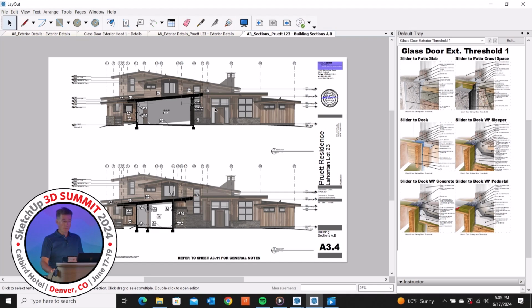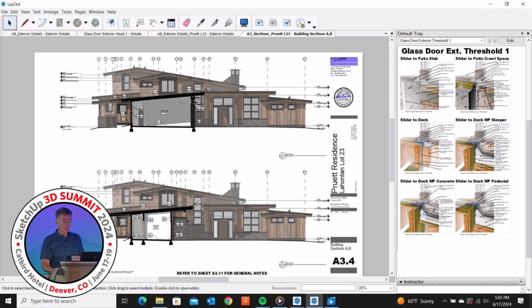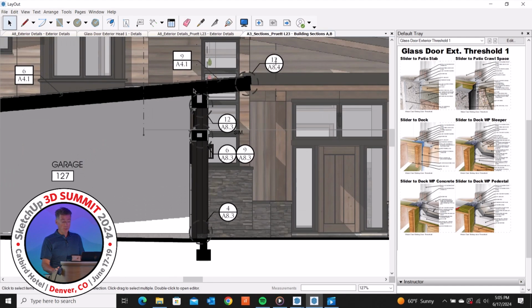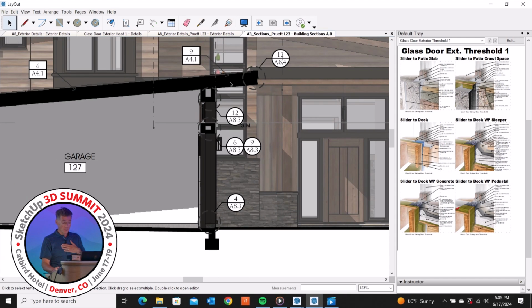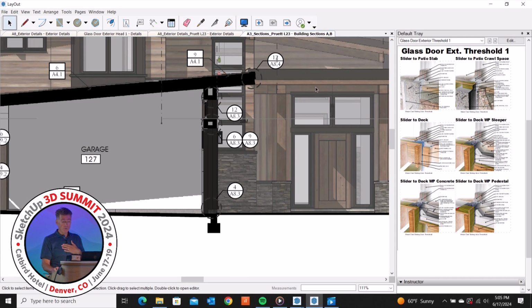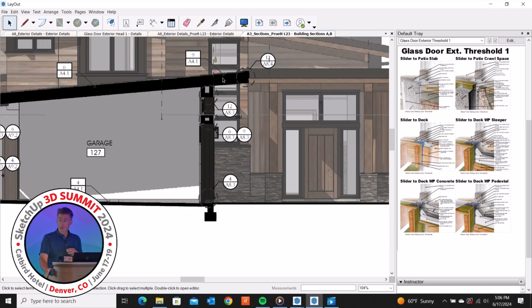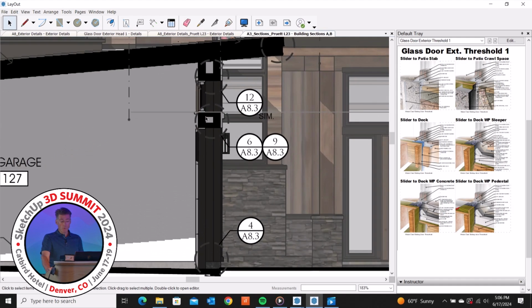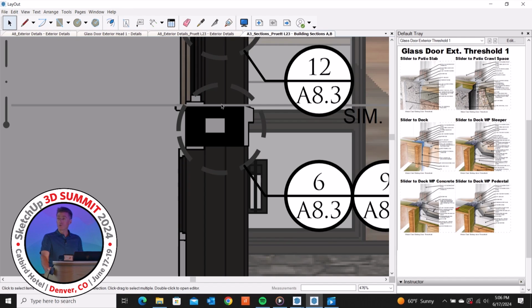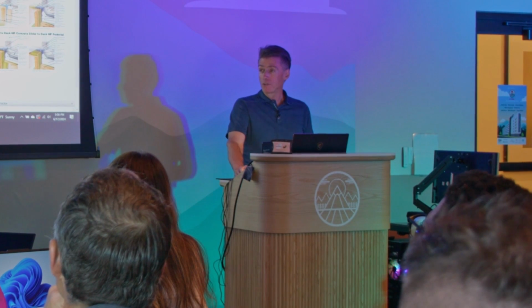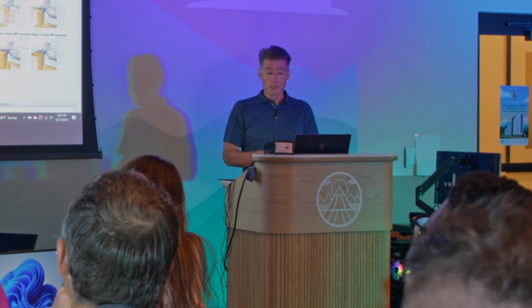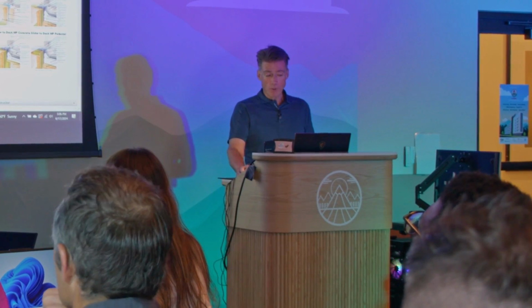Because as most of you know, I use actually a combination of stacking viewports. And it's pretty simple for sections and plans. I use the same three layers of stacking. I have the raster viewport in the back. I have the one that's very dark here, that's black. That is just the structure. So none of the trim is on, none of the doors, none of the windows, which makes it render, you know, an instant render even in 2021. And then the light gray one is just windows, doors, trim, cabinets, things that are just applied to the base structure. And I think it really helps read, and then there you can see how they're all keyed in.